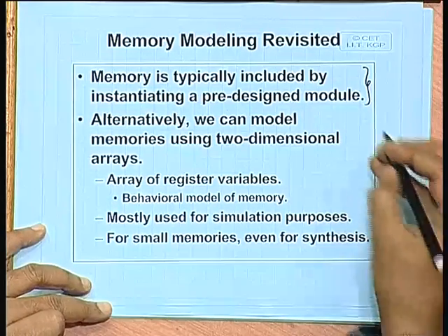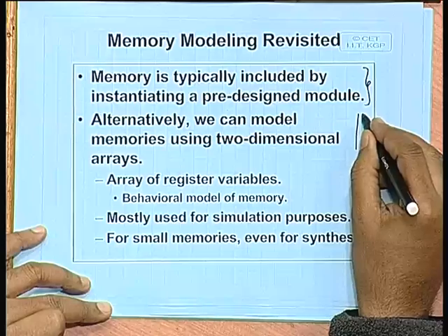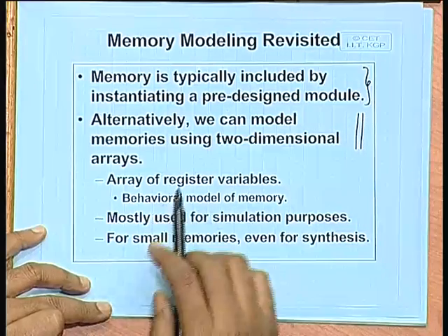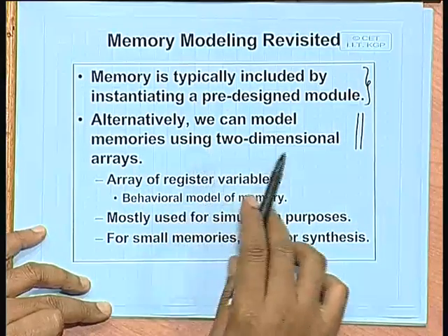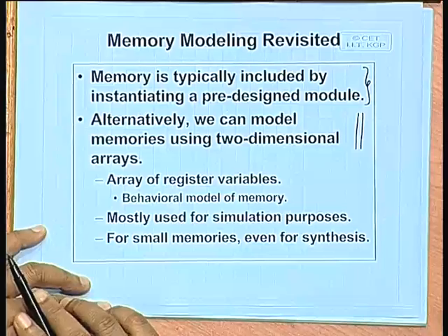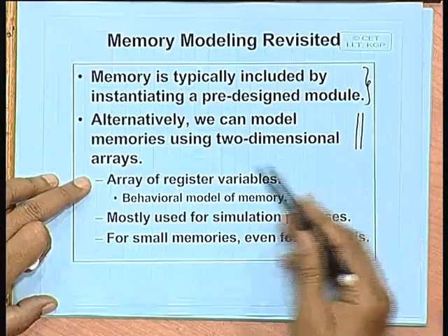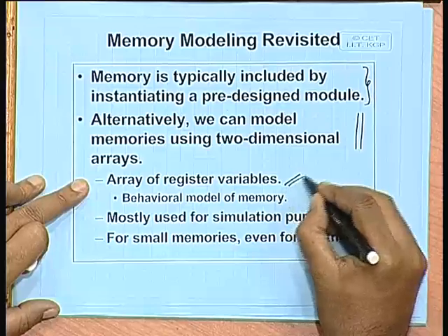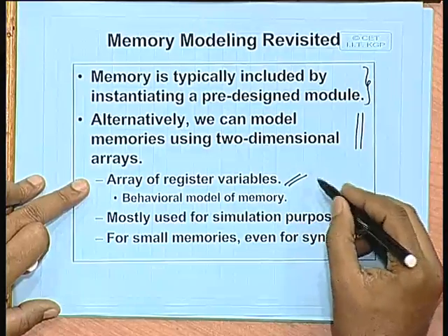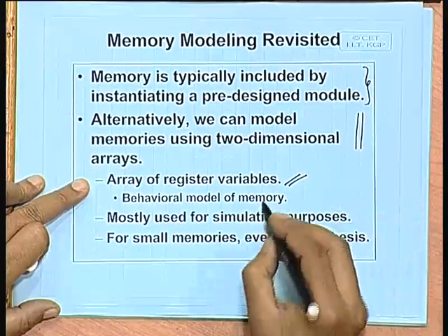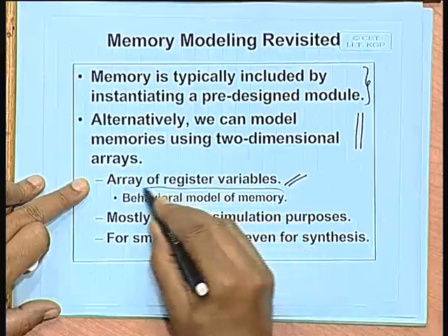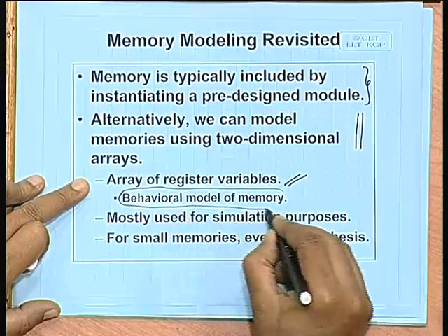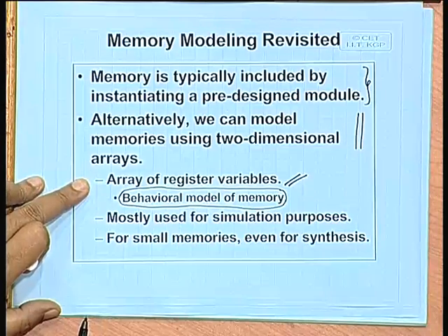So, as an alternative, what we can do, the language Verilog also supports this, we can model memory using 2-dimensional arrays. 2-dimensional arrays is essentially an array of register variables. So, you can treat it as a register bank. So, you can regard it as the behavioral model of the memory system.